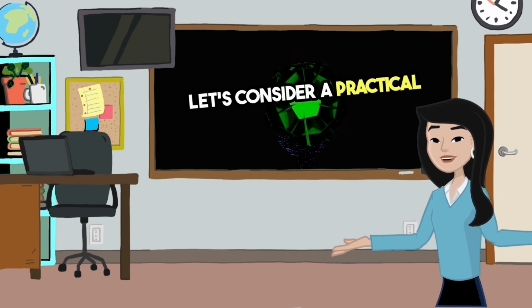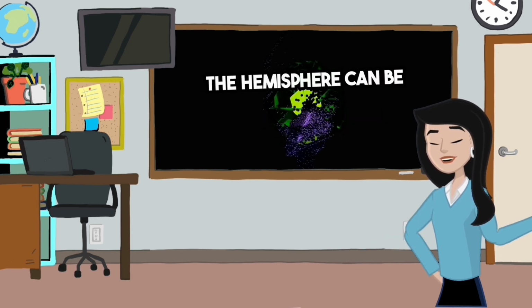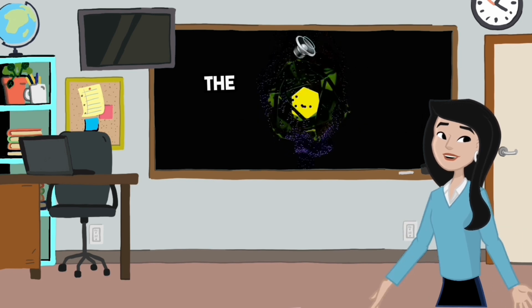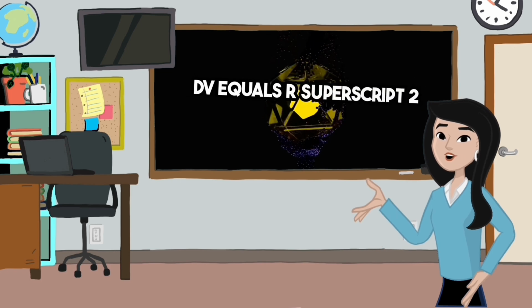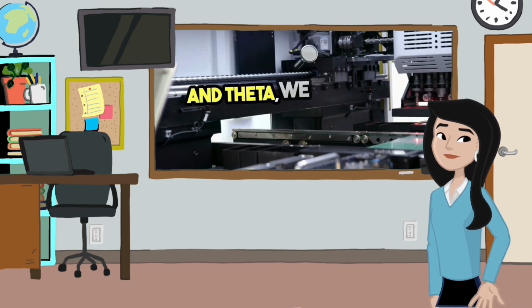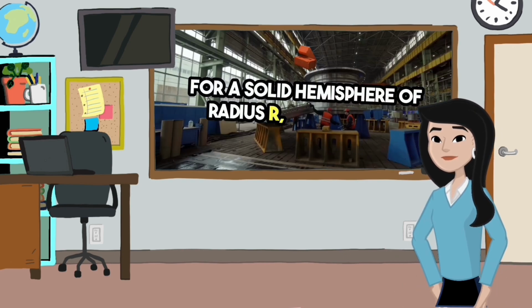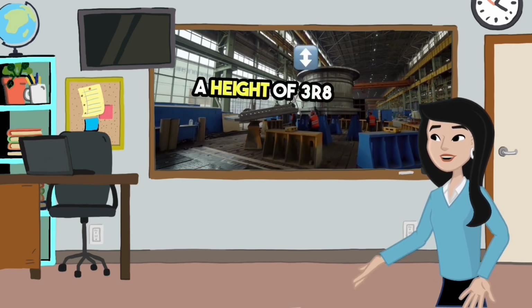Let's consider a practical example: finding the centroid of a solid hemisphere. The hemisphere can be described in spherical coordinates, which makes our calculations a bit easier. The volume element in spherical coordinates is given by dV equals r squared sin phi dr d phi d theta. By integrating over the appropriate limits for r, phi, and theta, we can find the centroid's coordinates. For a solid hemisphere of radius r, the centroid along the z-axis turns out to be at a height of 3r/8 from the base.